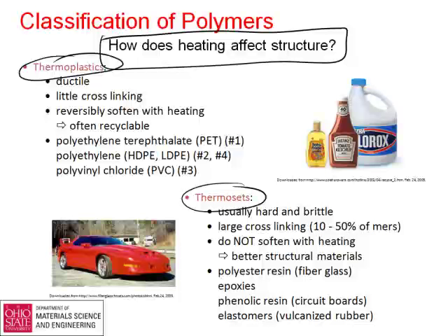Turns out that you do end up damaging the chain weight as you take them through the processing we'll talk about. So you can't keep reusing them as much as you would like, as much as, for example, you might be able to with aluminum, where you could remelt and resolidify and it doesn't change. With plastics, the chain weight does tend to degrade with time and working.